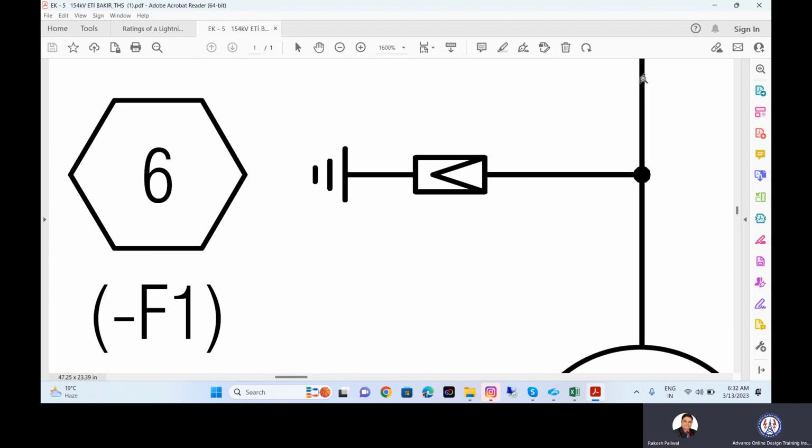If that is flowing, it means this portion is basically working properly. This is not grounding the high voltage, the 50 Hz frequency current. Only the normal leakage current, because of the phase to the ground.